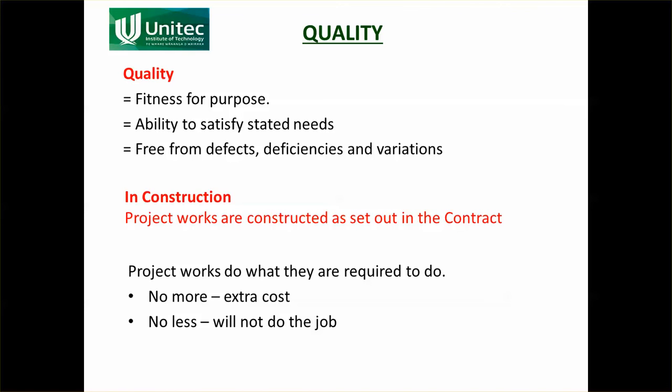So a good constructor will go to the designer or the client and say, look, we can do this faster and quicker if you do this bit differently. They might specify a different profile of curb, and he goes along and says, look, we can do it quicker and cheaper using this profile. You still have the same effect, the curb will still collect water, but it'll look different.